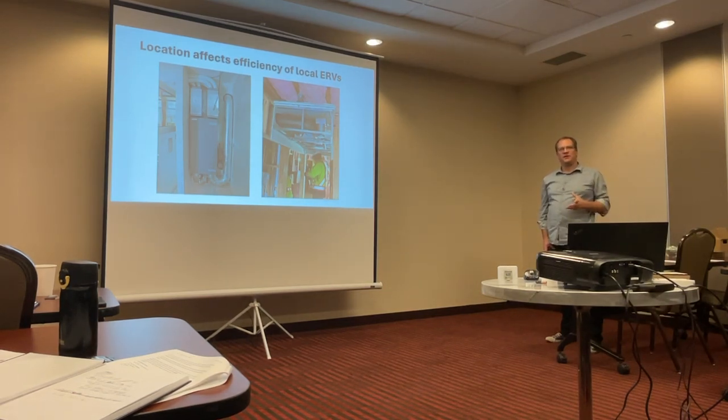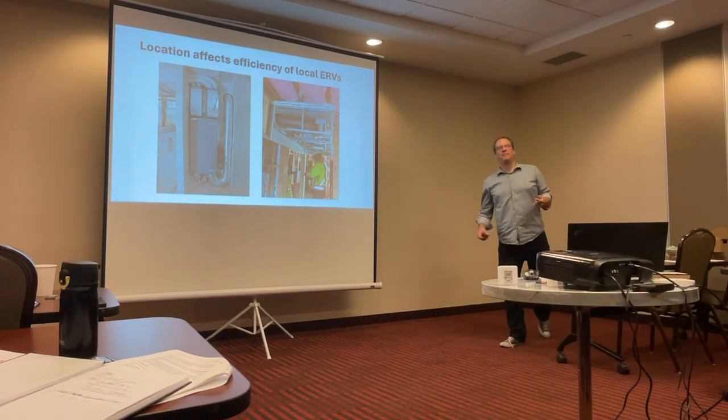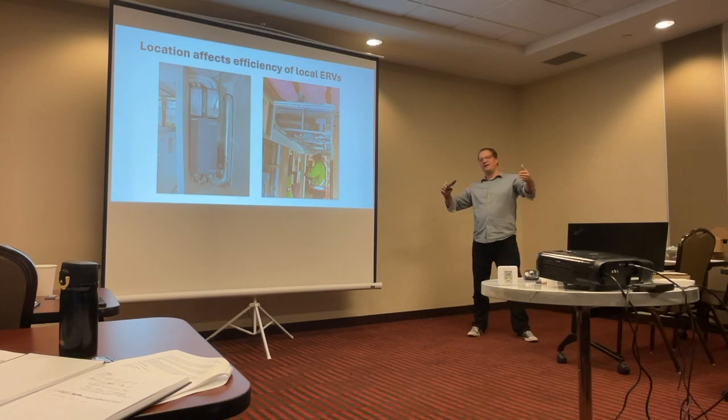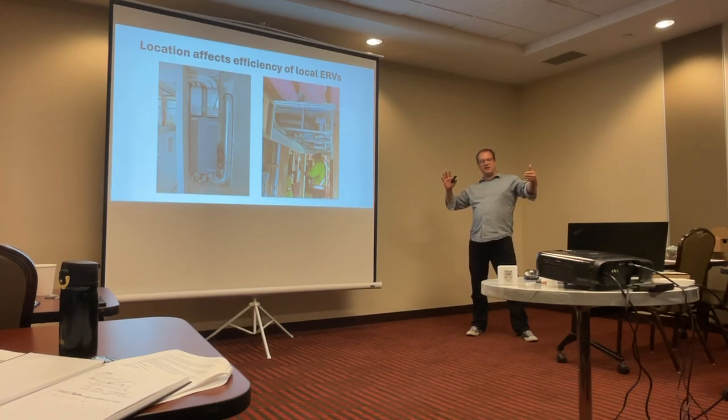And this is a modeling trick. Remind me of this. Sherman did a couple of great ones for us at RDH where we would show that moving the ERV away from the wall to where the bathroom was, which is usually quite a ways in, changes the heat loss calculation equivalent to like 2 extra inches of insulation on the building. Which isn't to say that's the only way to make it up, but that's how big a blow it is.